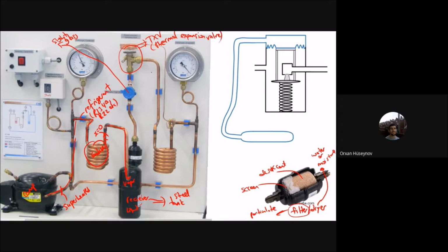Okay, and then the outlet of that thermal expansion valve, it will be a mixture. So here you will have that mixture, and then from that thermal expansion valve you will have the evaporator. Sorry, evaporator. This one is the inlet for the evaporator and this one is the outlet, and you go back to this compressor here, to the initial state, and the compressor compresses again, and you have the cycle here.